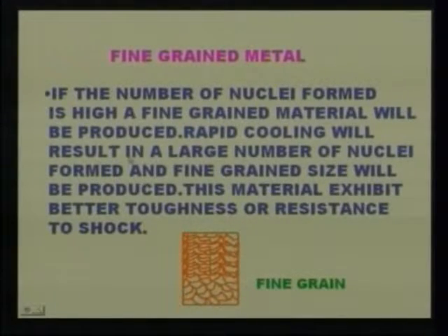Rapid cooling will result in a large number of nuclei formed, and a fine grain size will be produced. This material exhibits better toughness or resistance to shock. It also increases yield strength, tensile strength, etc. These mechanical properties are increased.